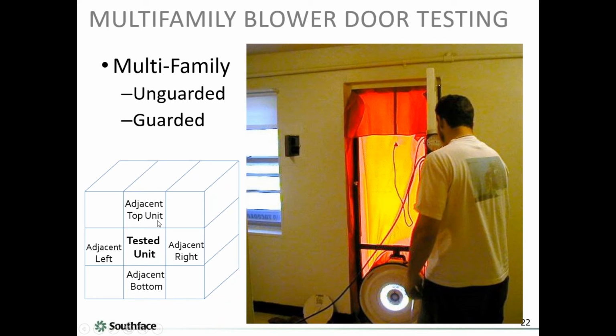Now let's talk about multifamily blower door testing. So multifamily testing is probably something that a fair amount is happening of because of code requirements that would require most multifamily structures to be tested. Or a program, yeah, an Energy Star or a green building program. But we've noticed from our experience that the way you conduct that test really has a big influence on the results. Are you trying to determine leakage across the party walls? Are you trying to determine leakage from the outside? What are you really trying to measure when you go in and perform a blower door test on a multifamily